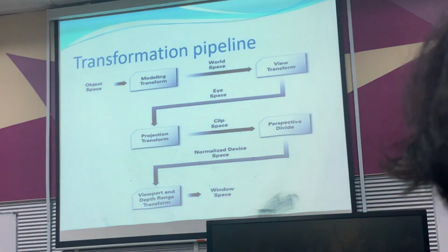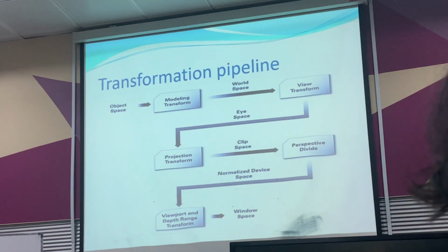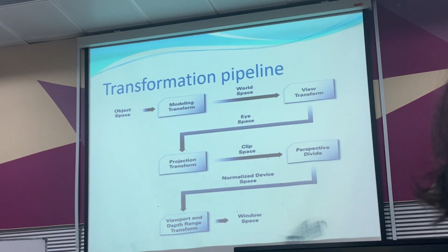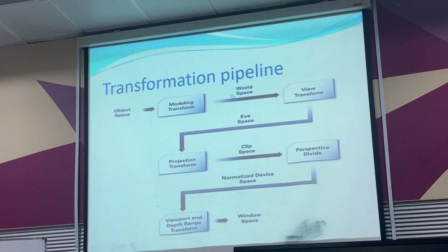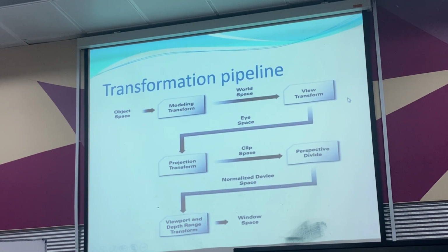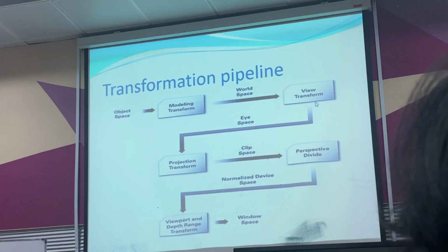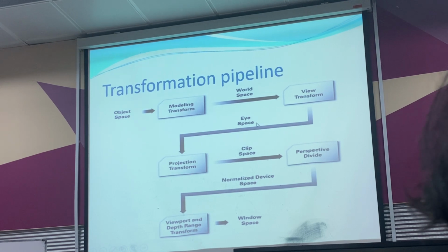Frame, to form a frame. And for you to put your transformation there, your TRS for your model. Your object, the vertex that you draw, is in the workspace, the 3D world. Then this one is what we're going to look at in chapter 5, which is your view, your camera. Your view transform, where you put your camera, and then your eye coordinate, where you place your eye on the camera.